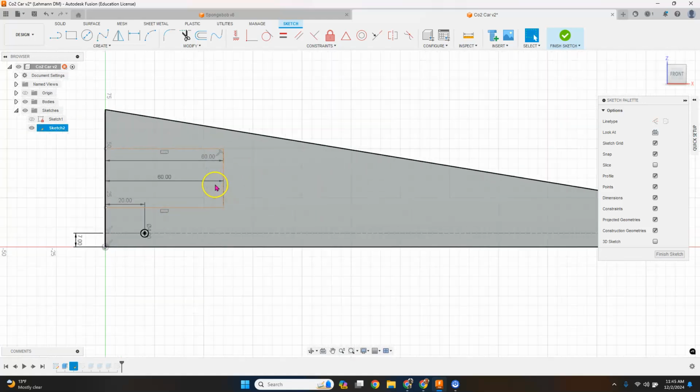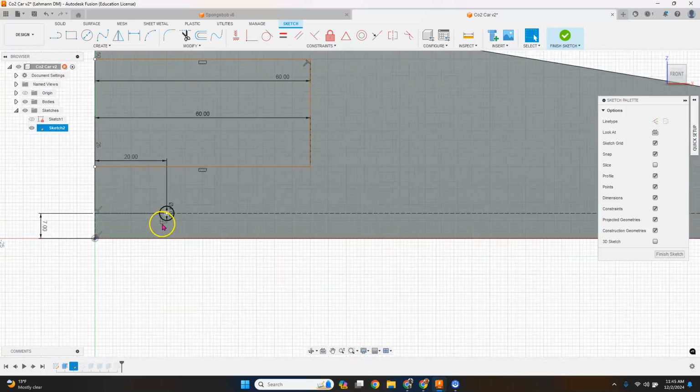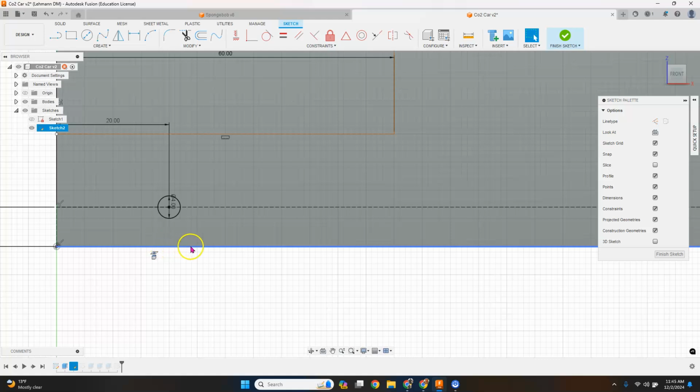Now, with that being said, what we want to do is basically draw a line from the back of our car, anywhere from this point up, starting around this area to the front of our car where it ends somewhere in the front portion. Underneath, we can also have things cut away, but we have to stop and we cannot cut directly underneath the axle hole. So wherever our axle hole is right here, in this area, we cannot cut away. We have to have our line come down and then across the back so we can extrude that portion out.